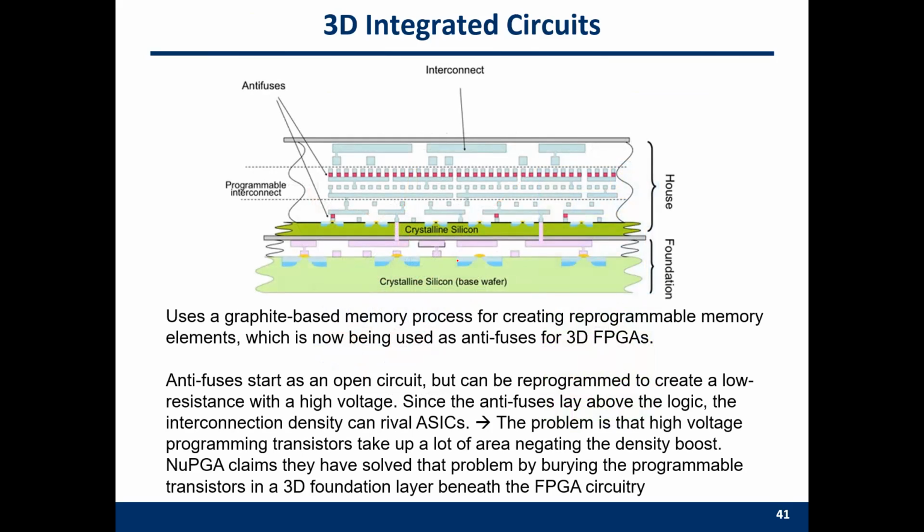So here is one example of the 3D integrated FPGA board. We can have a programmable interconnection layer like this. And then we have a bottom CLB layer and a top CLB layer. In this way, we can have multiple active device layers, but have the same area overhead because we vertically stack multiple layers together. Any question about this?